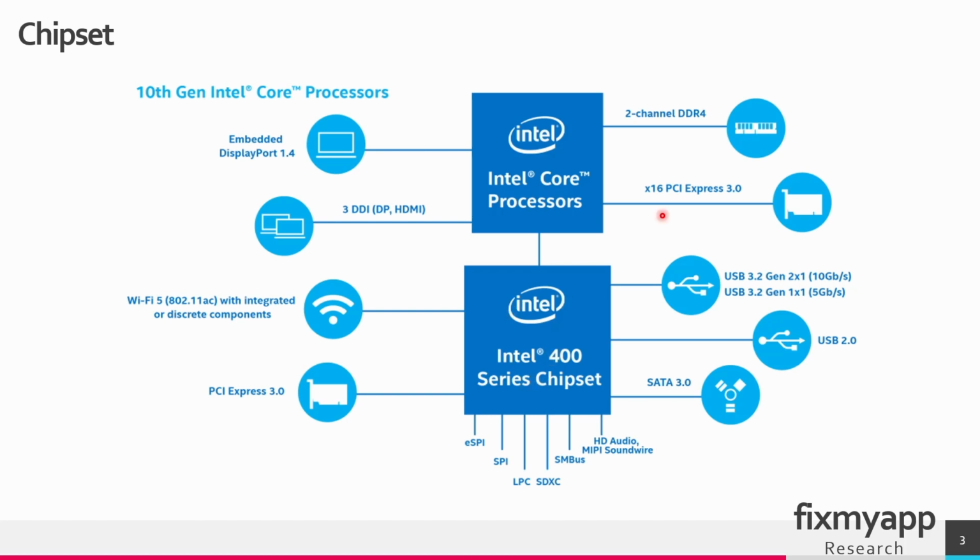If you want to connect an internal graphical card, please be aware that you put it in the correct PCIe slot, because we have low speed PCIe slots and also high speed PCIe slots. The difference is the low speed PCIe slots most of the time are connected to the chipset, so there are less data lanes available for this slot, and that is why the speed is lower, and also the data goes through the chipset and then to the CPU.